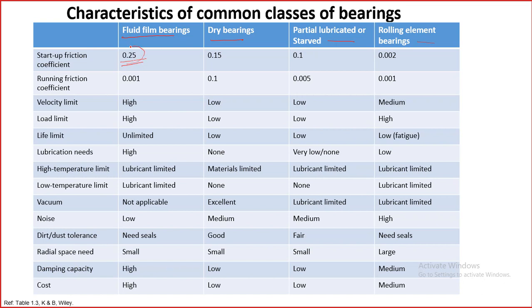So most of the lubricant will be in a bit of a viscous state, or sometimes it can also be starved in some cases. So for example, the lubricant may not be fully distributed all over, because it takes some rotation before it starts. And another reason is that hydrodynamic lubrication will not act unless the speed has reached some range. So in the beginning it will be boundary lubrication and therefore high friction.